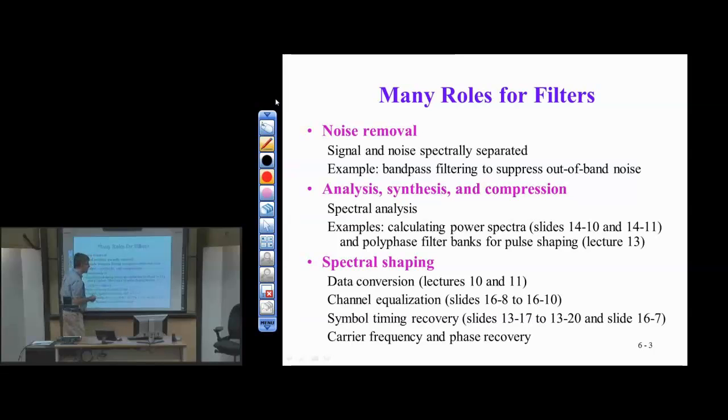In the Lecture 5 slides, Part 1, we talked about analyzing a complex signal, a regular signal, and breaking it into 2 bands. So we talked about taking a signal, x of n, that could have all frequencies in it, and we're going to break it into a low frequency band and a high frequency band. And there's some overlap between the bands. In the first case, we'll start with taking the input signal and passing it through a low pass filter, and taking the same signal and passing it through a high pass filter.